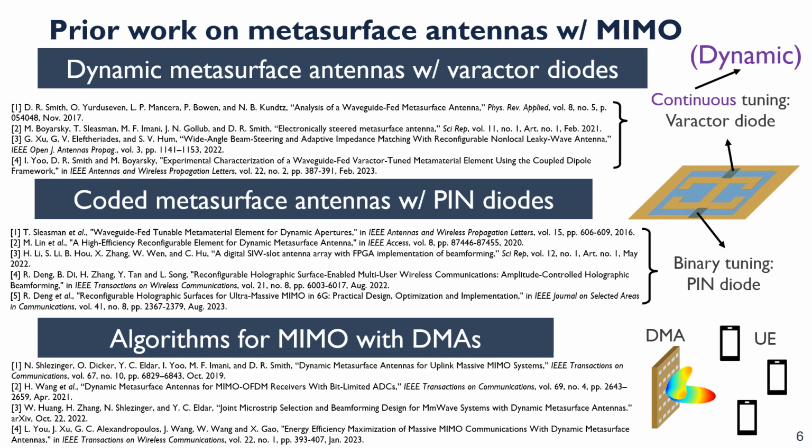There's been a large amount of recent work being done in the field of dynamic metasurface antennas, giving these potential power consumption benefits over digital and analog array architectures. There's been work with dynamic metasurface antennas using tunable continuous varactor diodes to steer beam patterns, and even create DMA prototypes where we can enable beamforming with this continuously tunable component for each of the DMA elements.